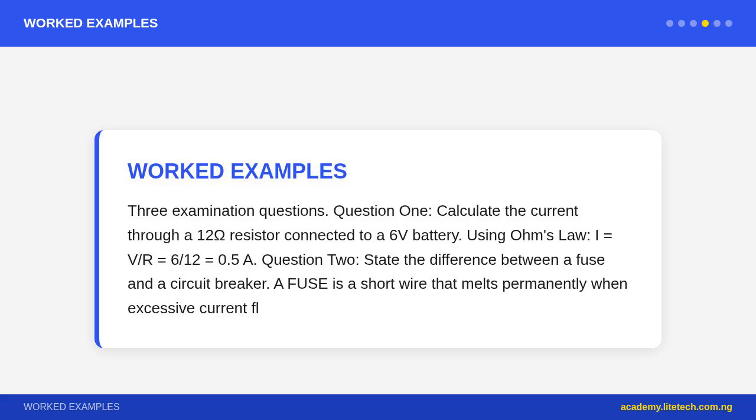Multimeter introduction. A multimeter measures voltage (V), current (A), and resistance (Ω) in one instrument. It can also test continuity, whether a wire or component is complete and unbroken. Three key settings: voltmeter, for measuring voltage, connect in parallel; ammeter, for measuring current, connect in series; ohmmeter, for measuring resistance, the circuit must be de-energized/off.